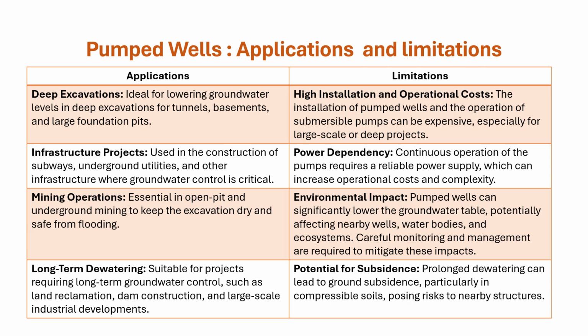And there is a potential for subsidence, because the dewatering may lead to ground subsidence, particularly in compressible soils, posing a risk to nearby structures. So those are the permanent dewatering techniques that are covered in this lecture.